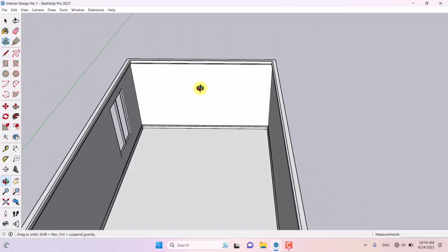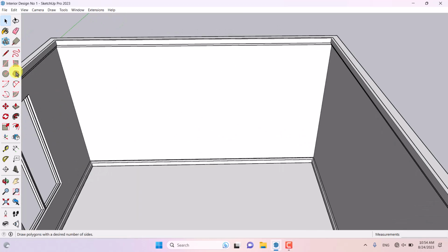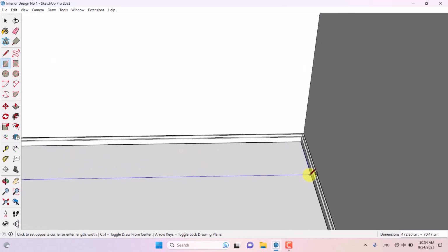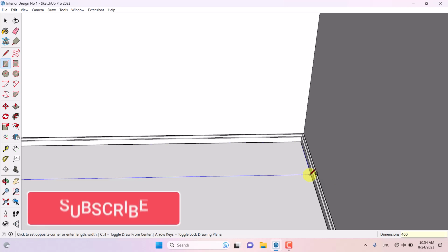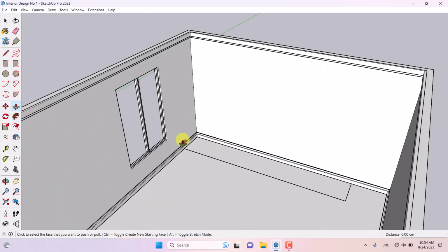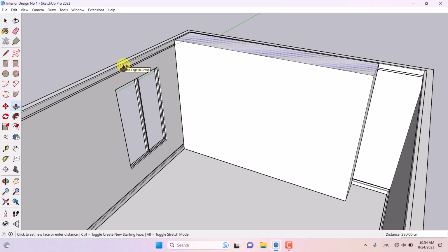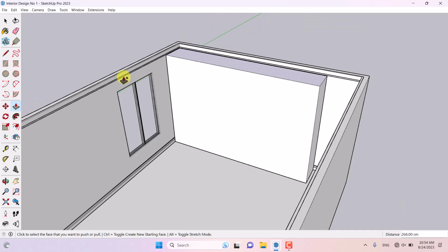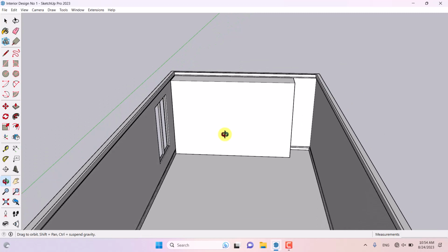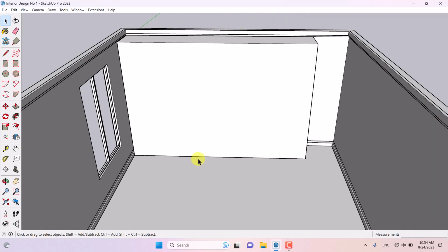And now it's time for creating the lockers and woodworks. So for this reason, I'm going to use the rectangle option in here again. Some number like that, for example, 40, 60. Alright, it's good. I'm going to click on the Extrude option and completely extrude it to the upside in here. So this is the locker for, for example, the living room or bedroom or any type of room you think it can be useful. So I'm going to partition it and create the units in here.